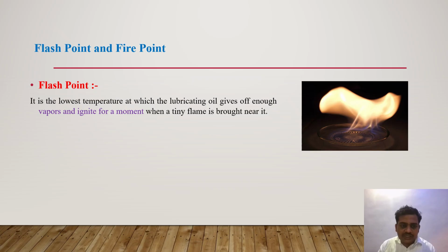Flashpoint is the lowest temperature at which the lubricating oil will give enough vapors and it will ignite for a moment when a tiny flame is brought near it.